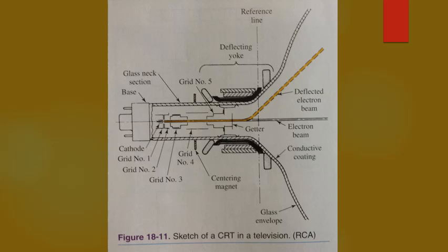Lesson in safety. Very high dangerous voltages are present at the external connections to this anode, usually from 8,000 to over 20,000 volts. Use caution when working close to these connections. Work only with one hand to reduce the chance of death from accidental shock. Keep one hand in your pocket.